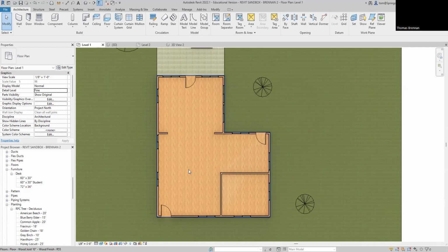Do we go from the outer point of the wall for the roof? Use this right here. That's your pick walls right there. And then go over here, and you've got a 1 foot overhang, you're good to go. Pick the wall, yep, there you go. Okay, so this is what you want to do here.